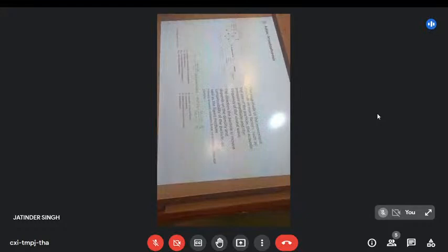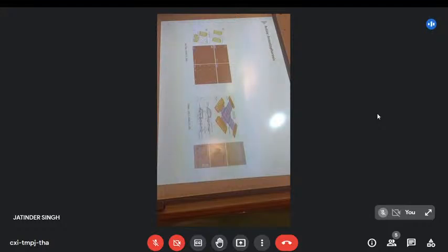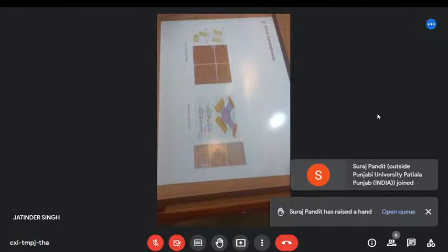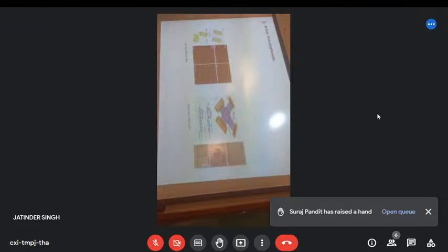I'll show you a couple of examples of what's being done microfluidically with these sound waves. Here we've got two acoustic transducers sitting at two sides of the channel. You can see that the particles line up in the multiple pressure nodes that are generated by these two speakers. If we put them perpendicular to each other, we don't get lines, we actually get different focusing nodes. So at two sides of the channel, we get lines formed in different nodes. If we put the speakers at both ends, then our high and low energy areas are going to be where those two fields coming from two directions meet one another.